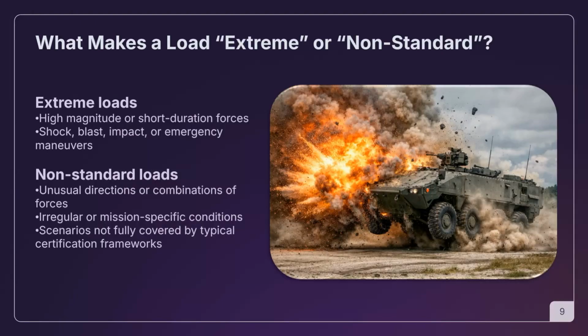Extreme loads often have very high magnitude and very short duration. We can outline here loads like shock, blast, impact, or some emergency maneuvers, where often the direction of the load is hard to predict. Also, analyzing these loads often requires nonlinear approaches, very complex analysis and complex load combinations.